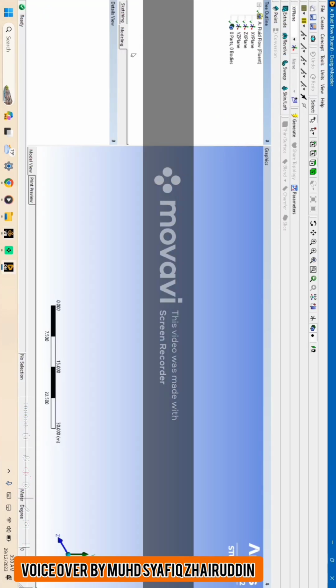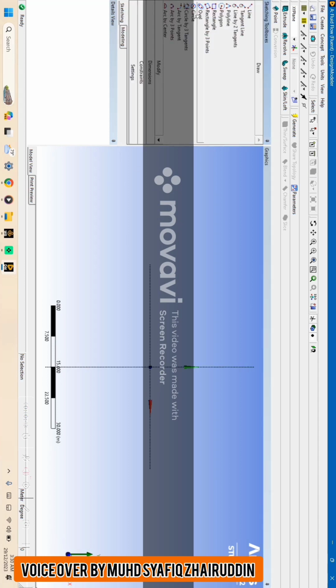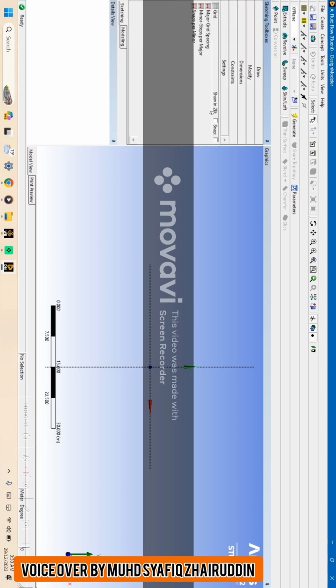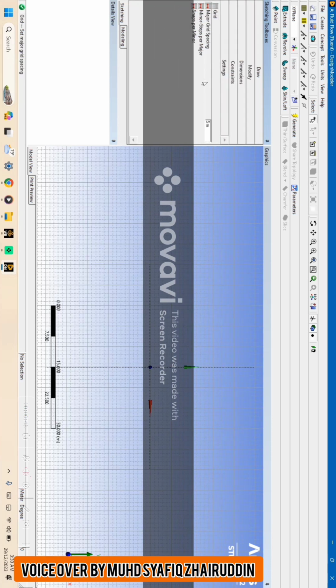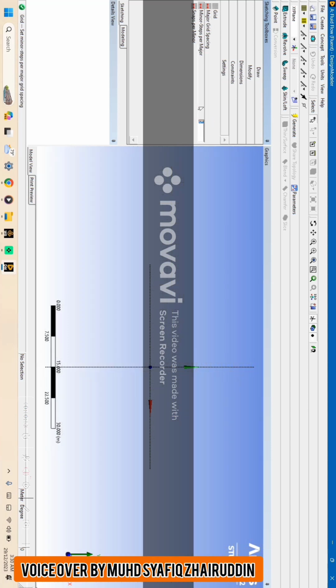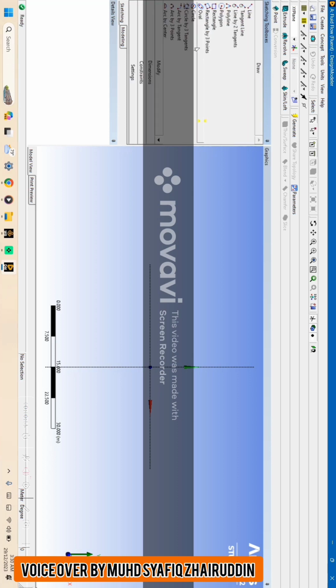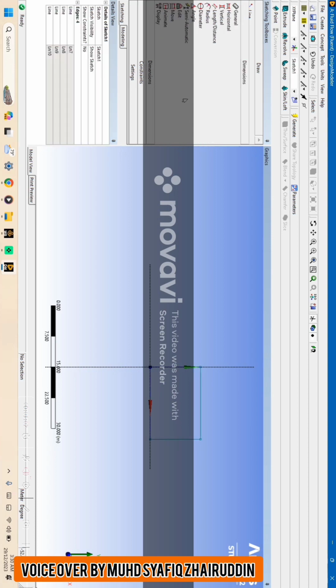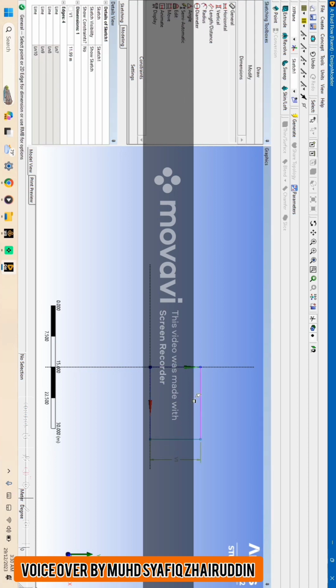Then you can see the new panel on the DesignModeler. Click the Z axis and Sketching and click Settings. Grid show in 2D, snap, measure grid spacing we put 0.1 meter, minor steps per major I put 10, and then click draw rectangle on the center point. So on the V1 and H1, V1 value is 1.5 and H2 is 0.3.